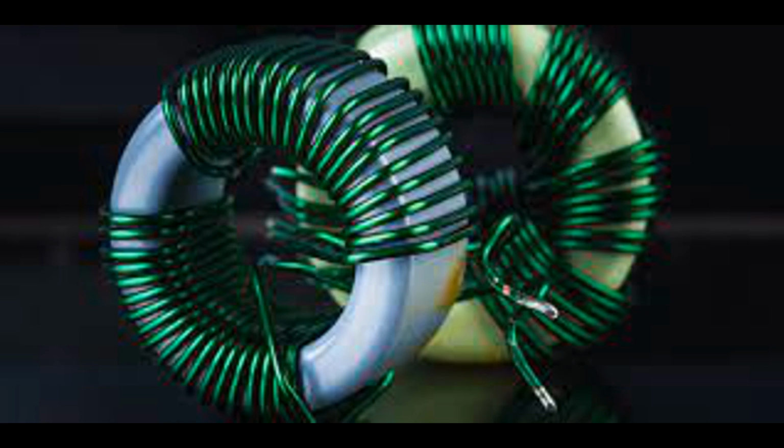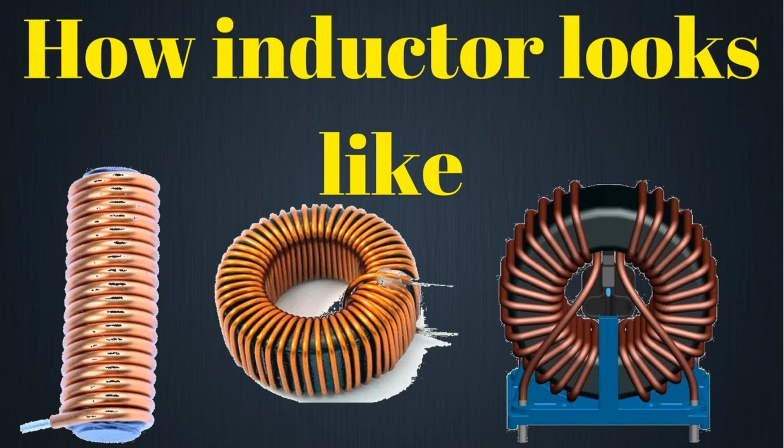out. Types of chokes. Common mode choke filters out noise or interference that is common to both lines of a pair of conductors, often used in EMI suppression. Differential mode choke blocks unwanted high-frequency signals in a single conductor or pair while allowing the desired signals to pass.